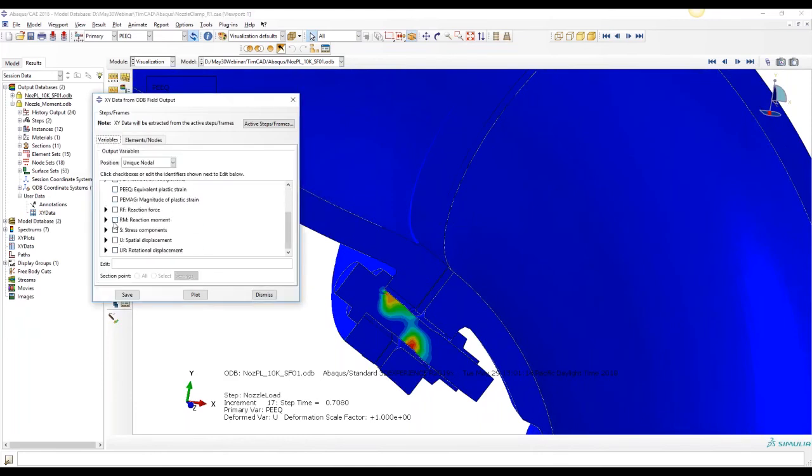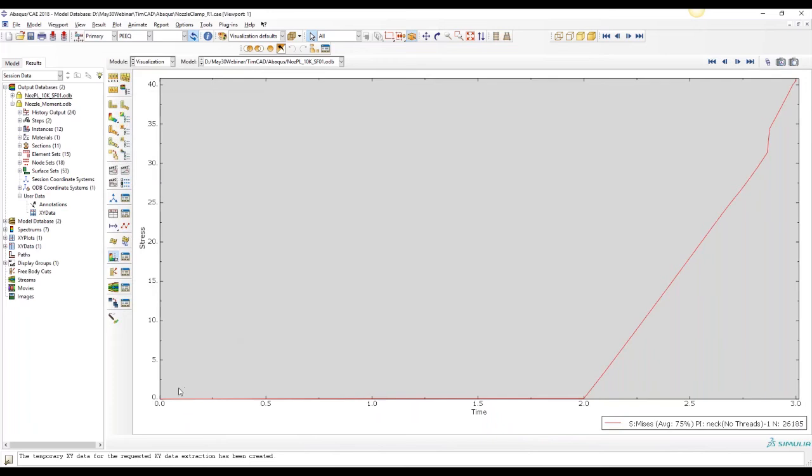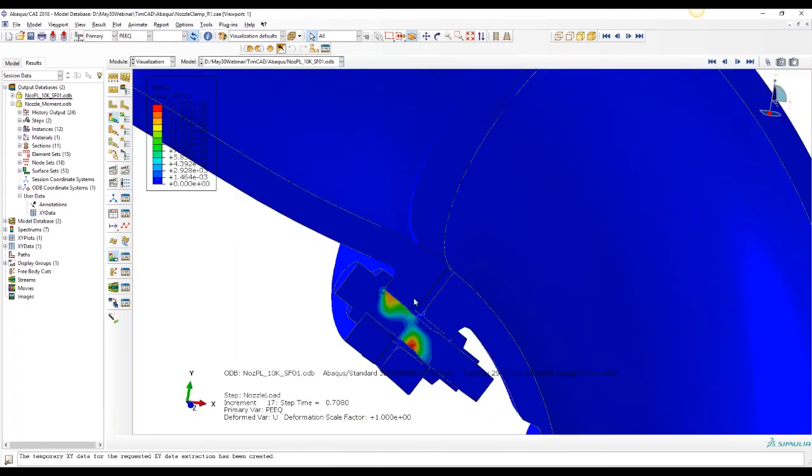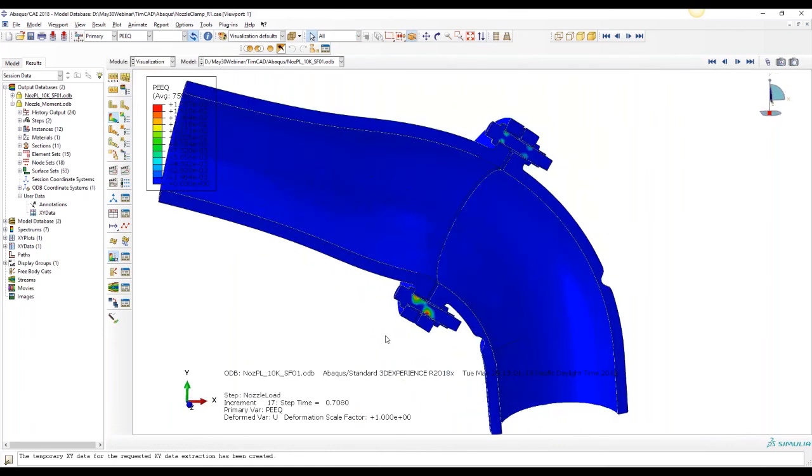And we can map some stresses to that. So this can be used in a variety of ways. They can be filtered. No real surprise, the stress is very low until we increment that ratcheting load up. But this allows you to do some numerical processing on this and go beyond just looking at a contour plot shape.